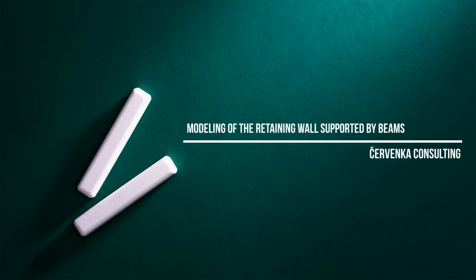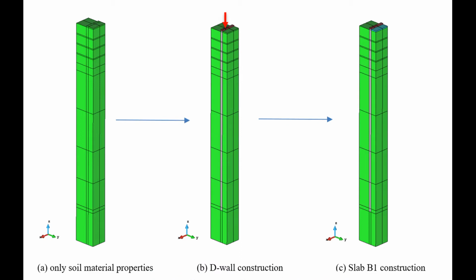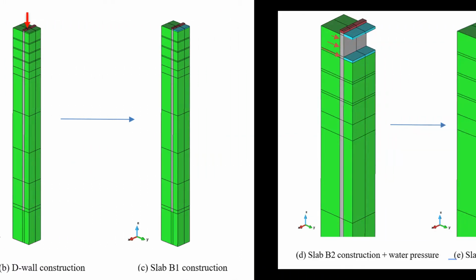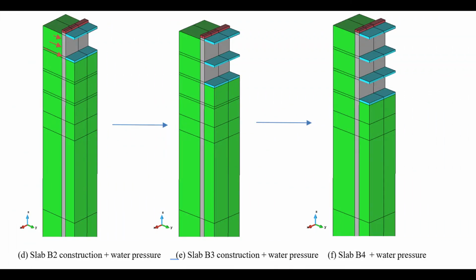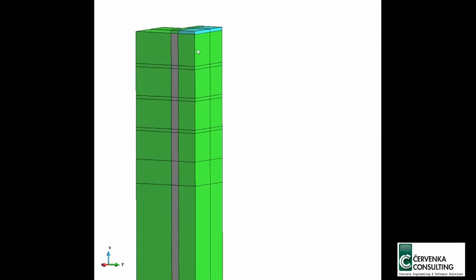We will review a complex example for the advanced level. The aim is to explain step by step how to use interval to divide work and simulate the real construction process, and how to solve some of the main problems we had during this process. Our example is a retaining wall embedded in soil.